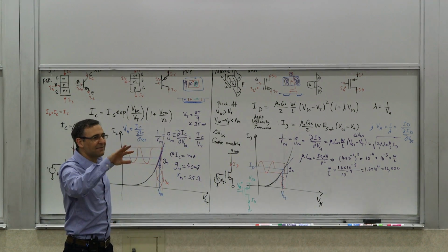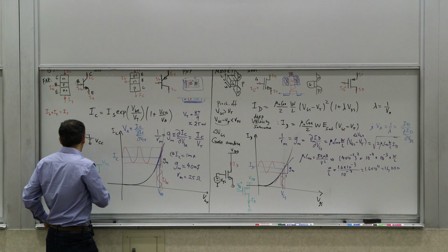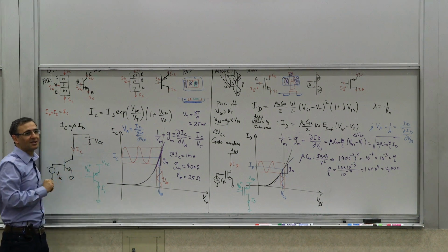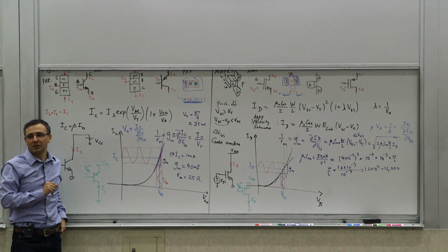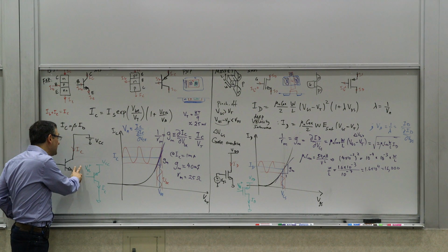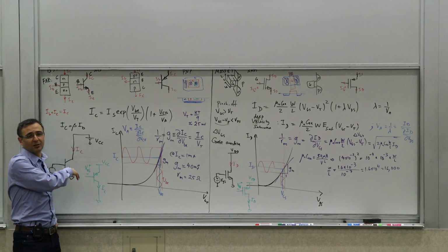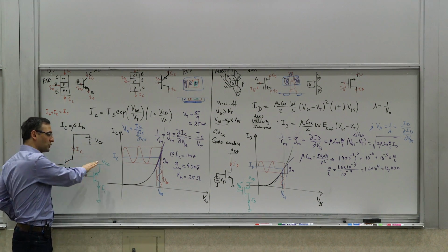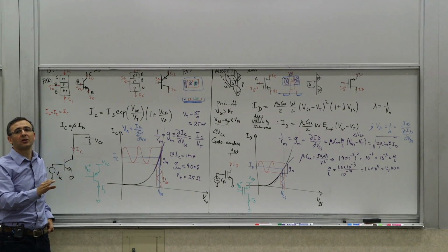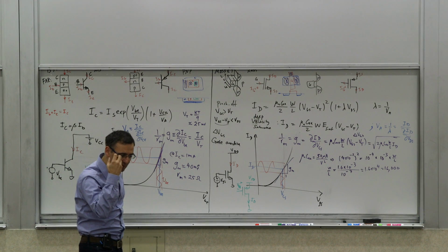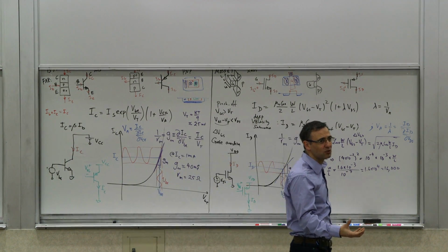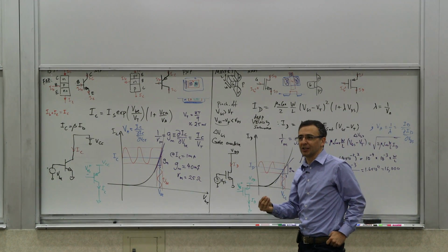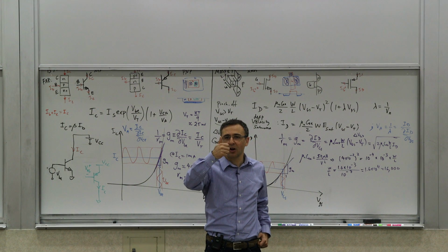Now, essentially, making switching gates out of these guys is harder. Now, in fact, you can still make really fast switching pairs with this. It's called ECL, with differential pairs, so that they don't go into saturation. But they are very power hungry because they have current consumption when they are not switching, because it's a differential pair that's constantly drawing current.